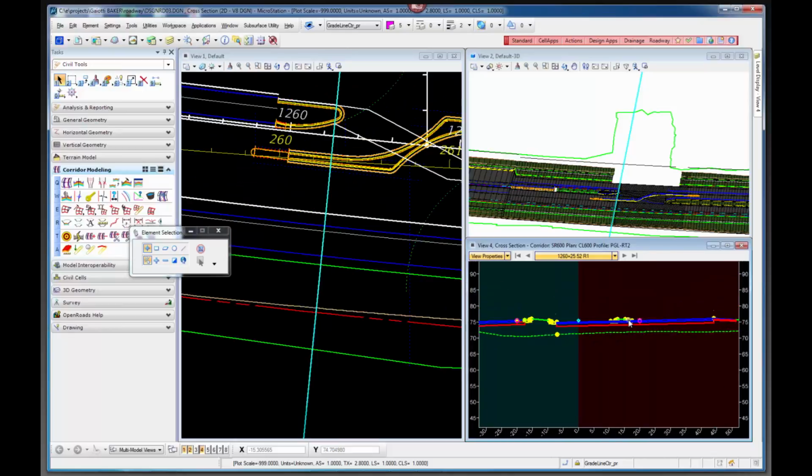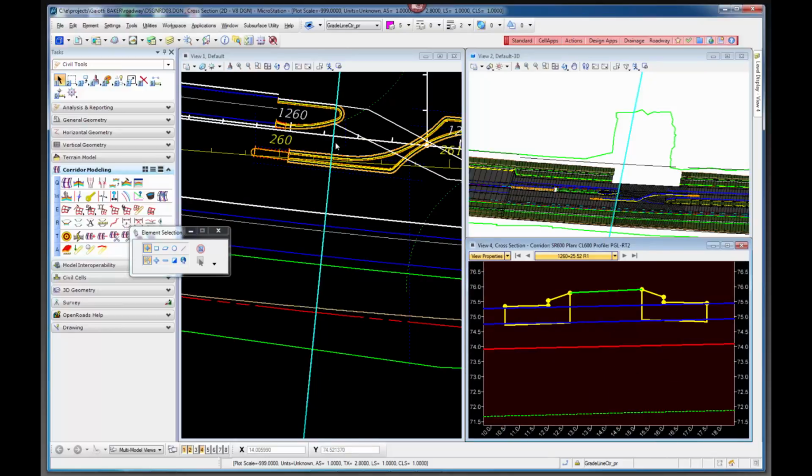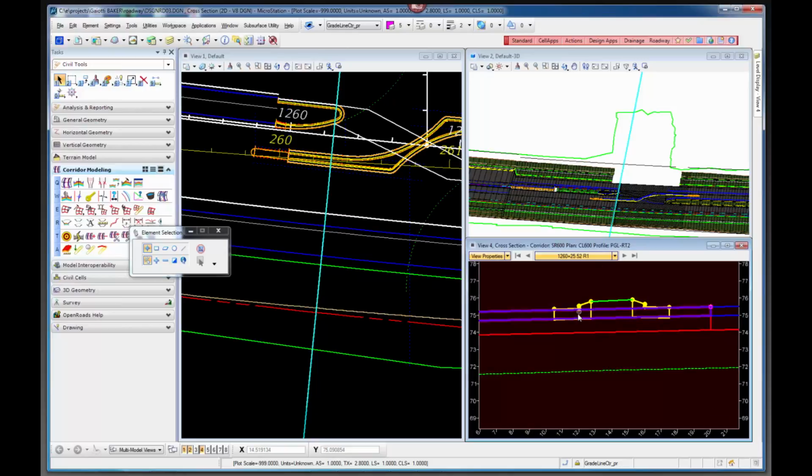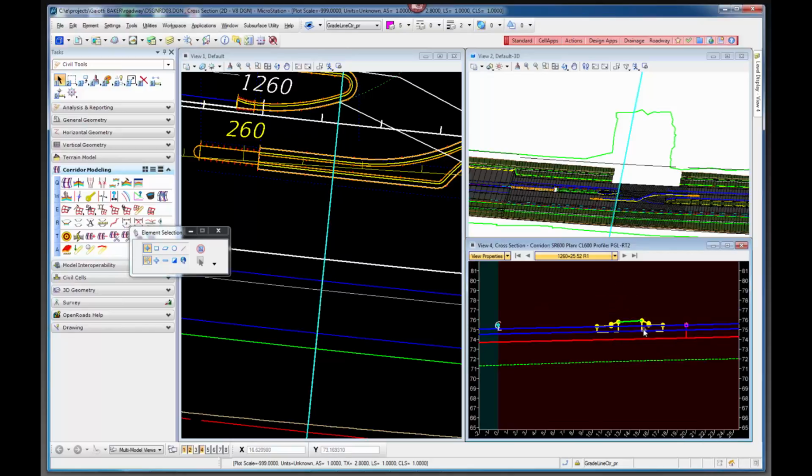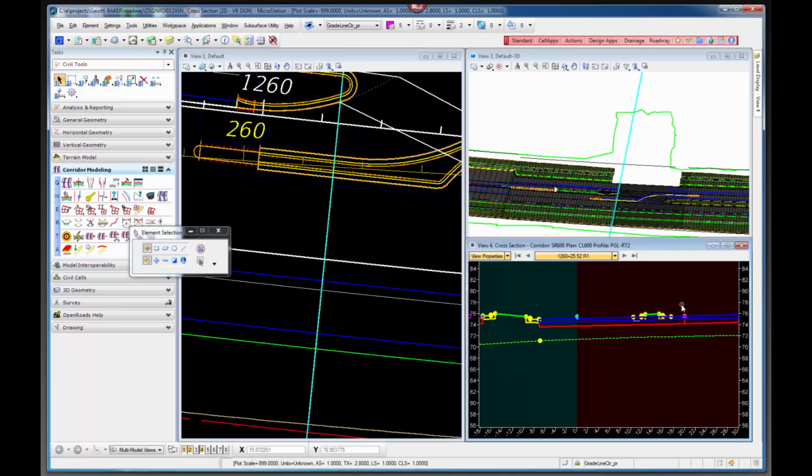You can see this is where the actual restricted turn lane is, where it's laying in there correctly, but it's not cutting out the pavement. You would need to add in these boundaries. You can place a boundary shape around there and cut that corridor out. It just adds additional processing time.